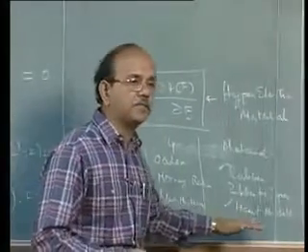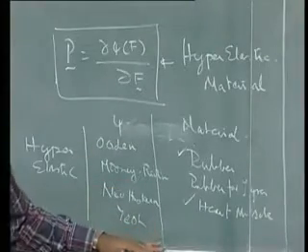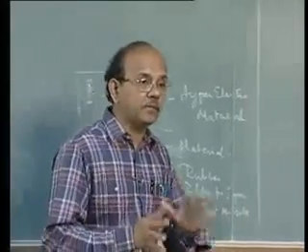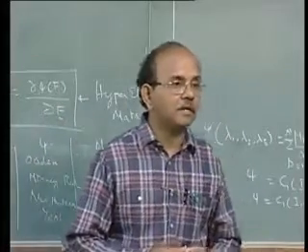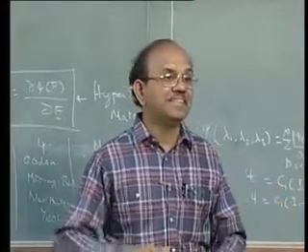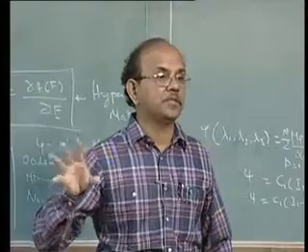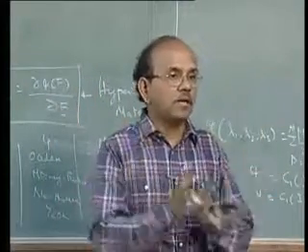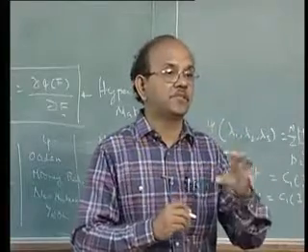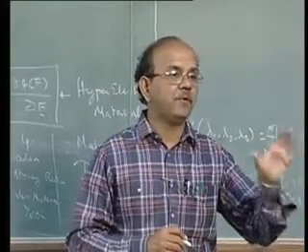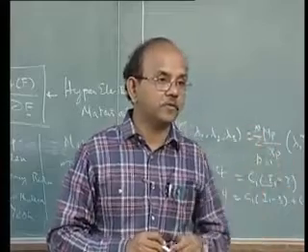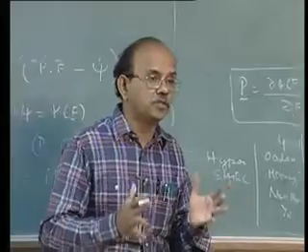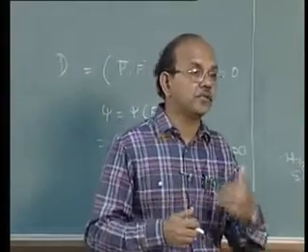For example, if you take a heart muscle, there is a strain energy function by Hunter. Now he has looked at the mechanical behavior of the heart muscle and said that, look, if this is the behavior, then this is the type of strain energy function which is closest to the behavior. Or in other words, all classes of heart muscles can be represented using this type of strain energy function. So there have been people who have been working on this for a very, very long time, the constitutive equations, how to put forward strain energy functions.